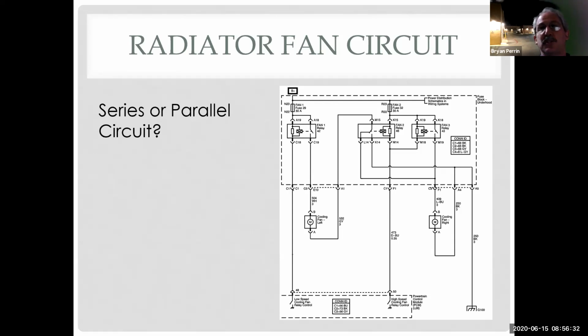I can use the scan tool to turn the relays on and see if the fans work, which means I don't need to wait for the car to get really, really hot before I go try to check to see if I have 12 volts or 6 volts or anything at my fan. I can do it on a cold engine and just use the scan tool to turn it on.